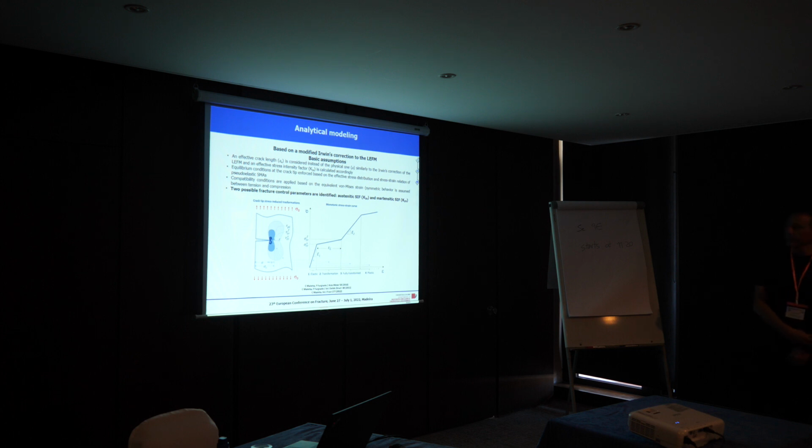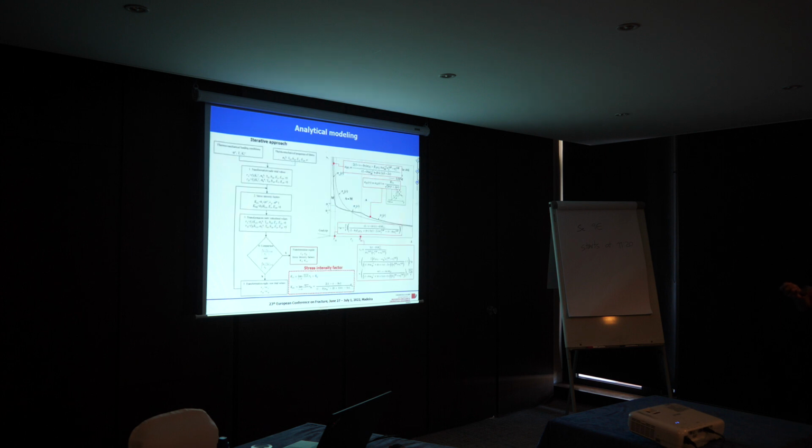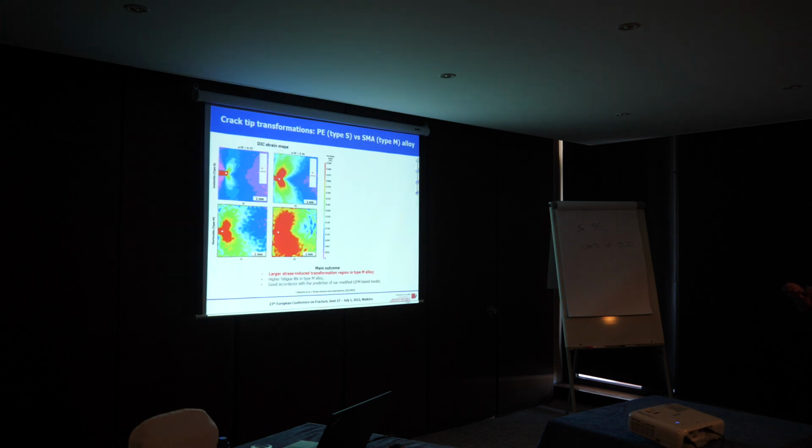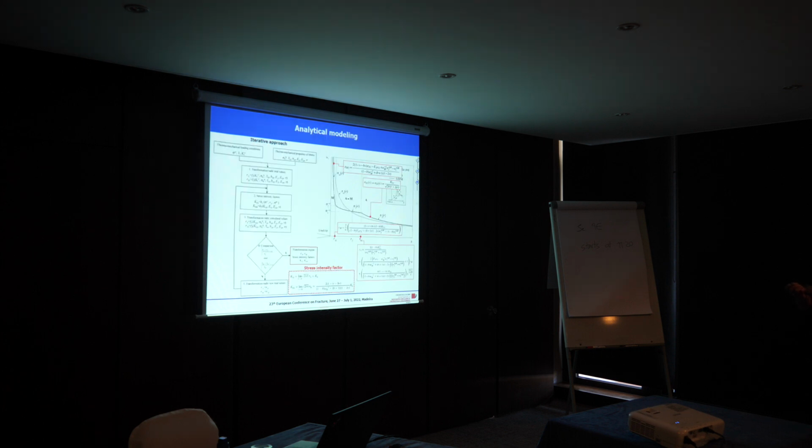Thank you. Yes, please. Along the same line a bit. So you use the Williams series to fit on your strain data from digital image correlation, right? The Williams series is an elastic description, right? But at your crack tip, you do have your phase transformation. So, I missed that part actually. How can you still just fit basically the Williams series onto this material, which has of course much more complex material behavior?